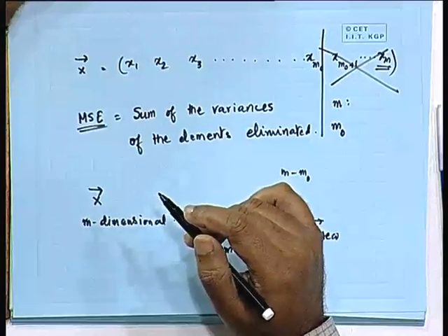It is based on some definite kernels which exist. But one difficulty is that this is based on some fixed kernels. You talk of the DCT or DFT, they are based on some fixed kernels, say for example, in the case of Fourier transform, the kernel is a complex exponential kernel consisting of cosine terms and sine terms, or the discrete cosine transform that consists of the cosine terms used as the kernels, as the basis function.